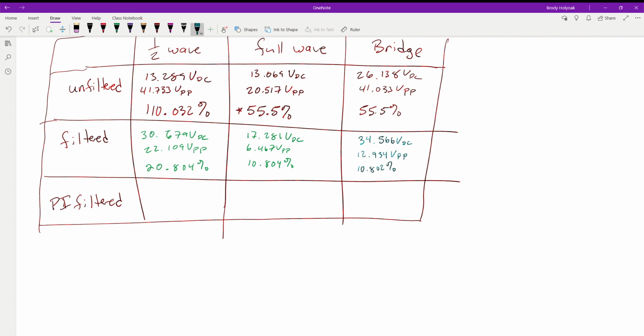A lot of times, you could look at, like I said, your power supplies for your computers, laptops, chargers, whatever, that has a little box that you plug into the wall. You could measure that output and you can actually see, okay, it says here that my output is supposed to be 15 volts. And sometimes they'll give them a rating. Sometimes they're just listed on the data sheets. You can go through and find them and be like, okay, how good is this power supply? And then you're like, okay, what can I build?